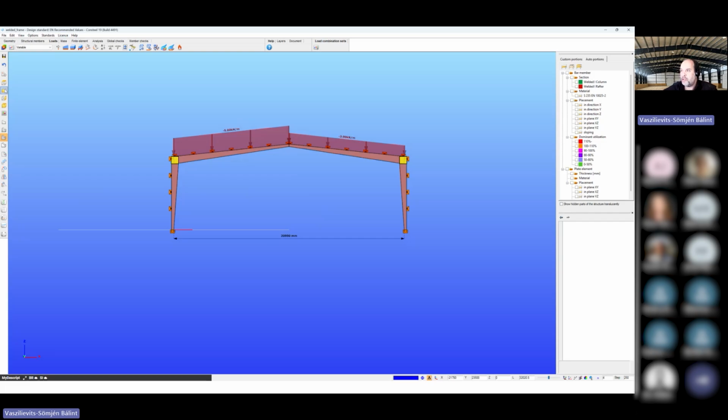We use for the buckling verifications the general method. The general method is out of plane only. This is something that we always repeat, and you should not forget. The general method is an out-of-plane verification. That's why if you look to the Eurocode, the slenderness used is called lambda OP. OP means out of plane.